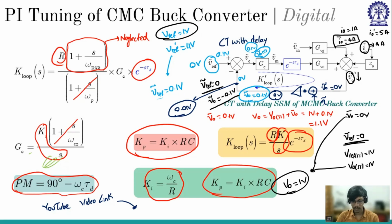Is this part clear? This limit of FSW by 10 is saying that the small signal model will reach the new steady state only up to that FSW by 10. Beyond that, it won't reach a steady state. Yes, it is not that it will not reach. The model will only let us design a controller that has a bandwidth of 1/10 of the switching frequency, and that decides the speed of the controller.